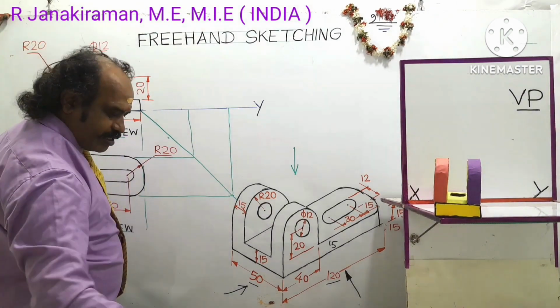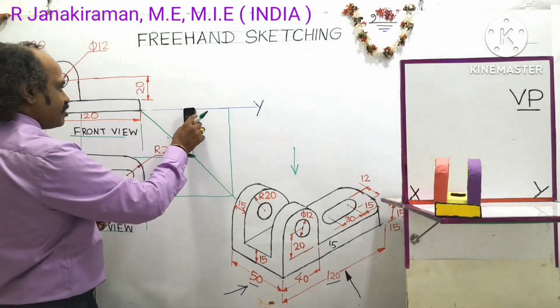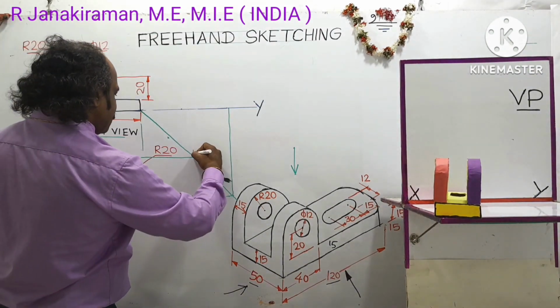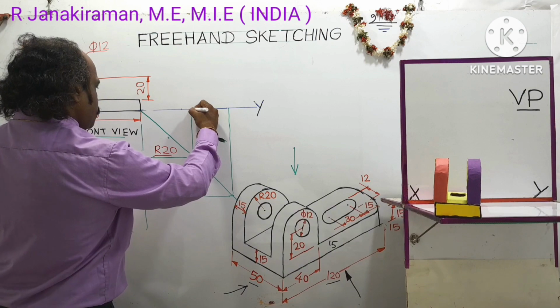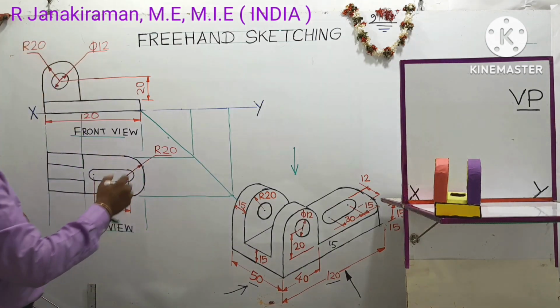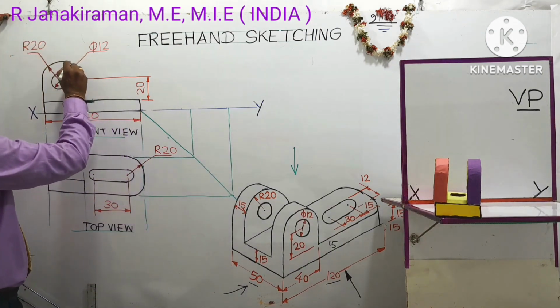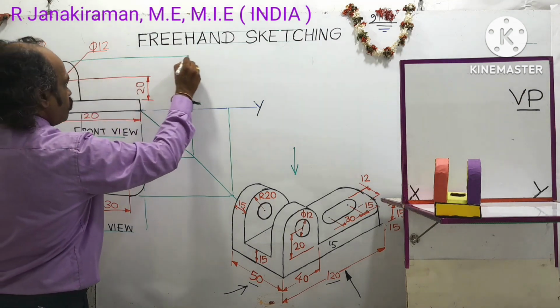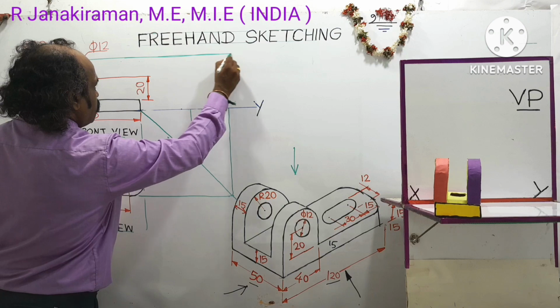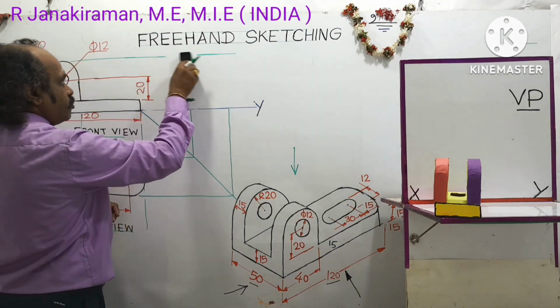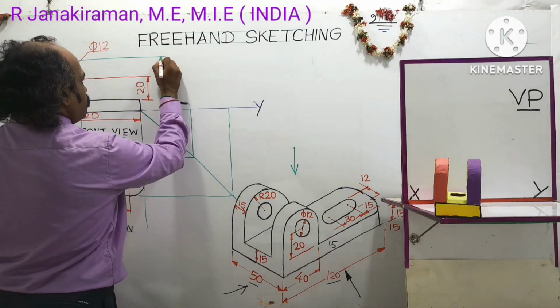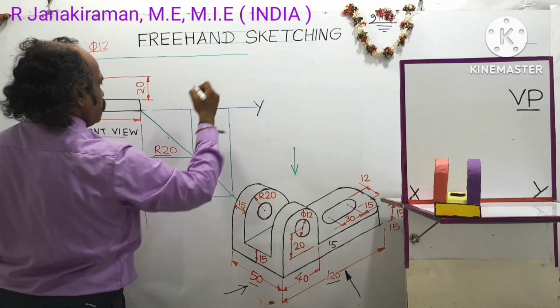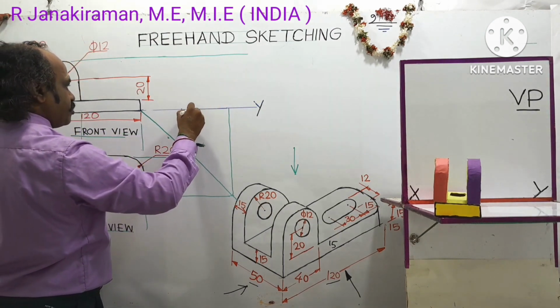Don't paint the line. If the line goes across too far, you can correct it by erasing part of the line. Okay. So next you project the previous front view top edge. So you extend this vertical projector.